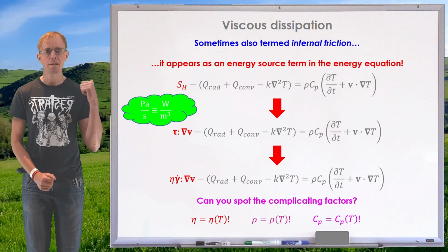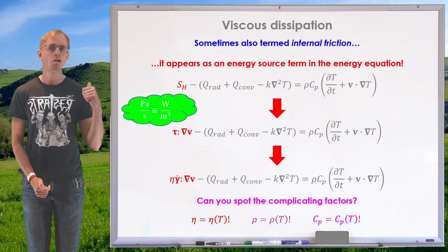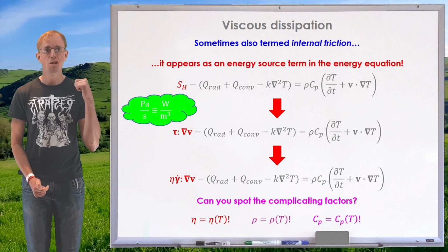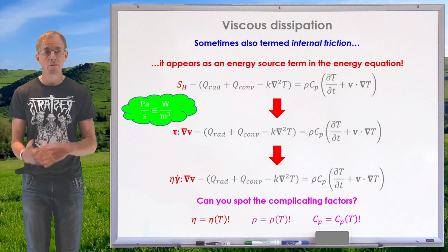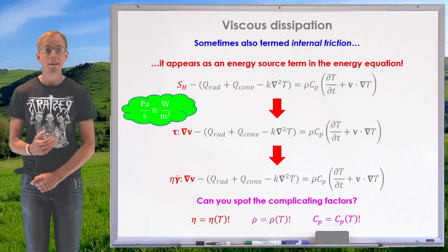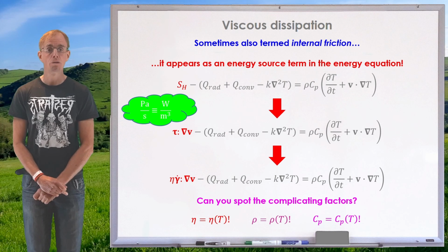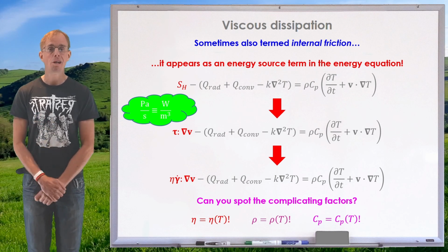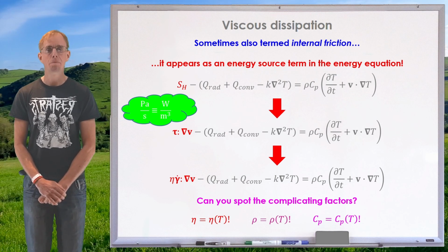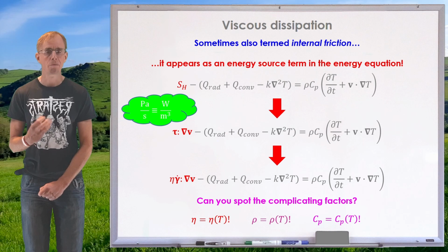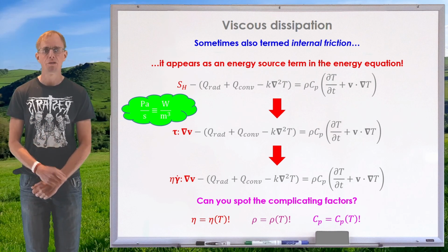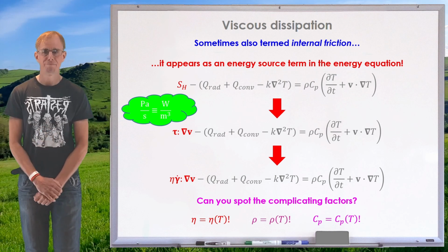It might not be. Viscous dissipation can be a major source of error if you're measuring the viscosity of materials using rheometry at high shear. Capillary rheometry is one high shear technique, but equally we can generate pretty high shear rates in rotational tools as well, and again, viscous dissipation may be an error source in the data that you're obtaining, especially if you're dealing with materials that are polymer melts that have a very high zero shear rate viscosity. So please be aware of this.